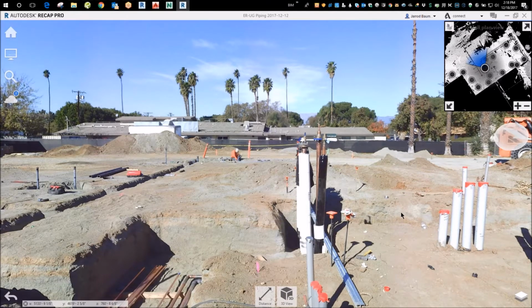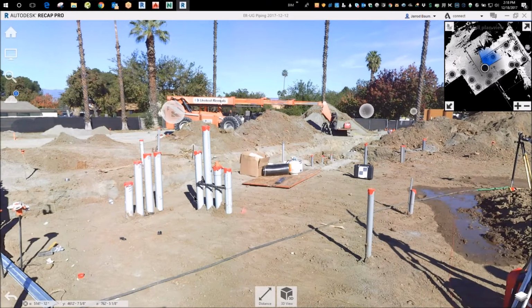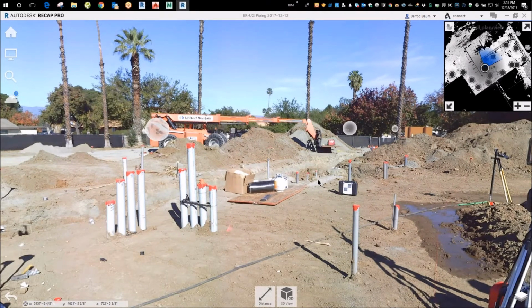I'm just curious, what coordinate system does everyone use universally? Like, is this the GPS or like northing 4,525 point something? So that would be what you'd call a local coordinate system, because the state of California is on state plane coordinates, which are mapped out in zones, and then all those coordinates will usually be around 6 million, 1.8 to 2 million in the area we're in. You go to the north part of the state, the numbers will be different, but they're working in that size coordinate system, and that's what California uses.